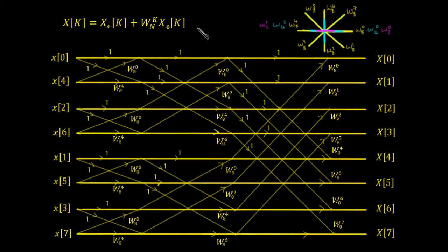I've also written the FFT algorithm up here on the left hand side for reference, and on the right hand side here I've drawn out the phasors. So again, we've got the phasors in yellow, which are going to be the 8-point DFT, so that's going to run W8 from 0, 1, 2, 3, 4, 5, 6, 7. So we've split the circle into 8 parts, so if you like, at 45 degrees or pi by 4.